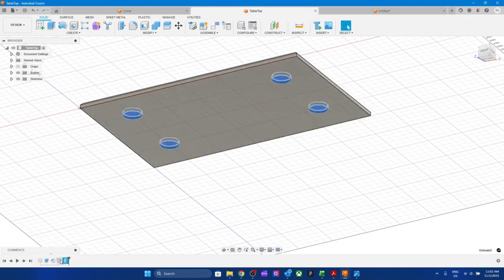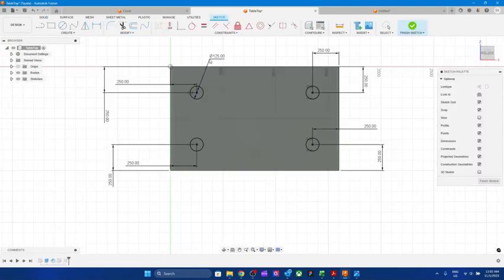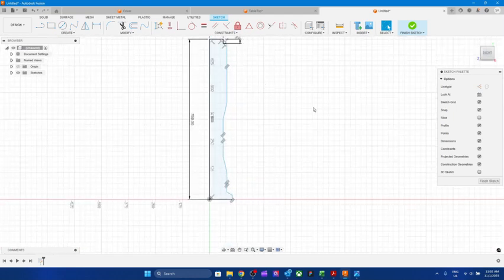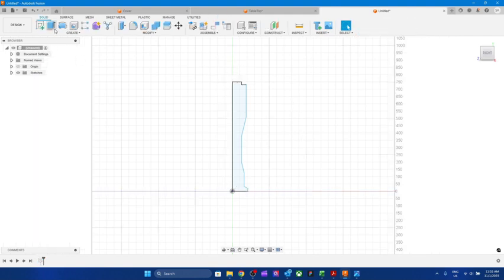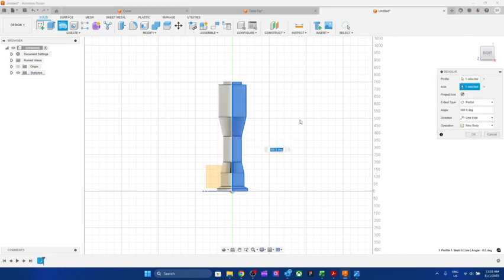So let's go back to this, edit sketch, 125. So in the revolve, you're creating half of it, because you will see what happens now, okay. So once I'm happy with this, I can put some dimensions. See, it's moving at the moment, so I can put some dimensions, but let's exit, and I want to select revolve this time, and it says axis. I want to select, so whole object is selected, section is selected. I want to select the axis, and it's going to be this, and you can see what happened.